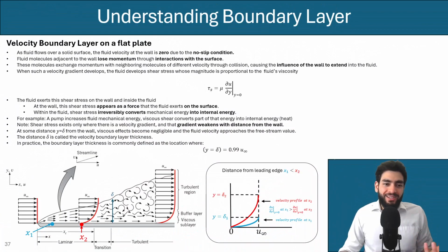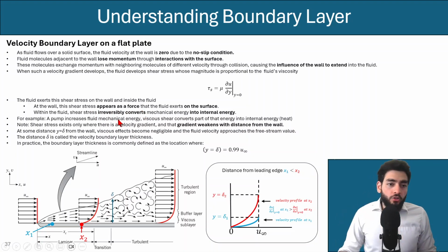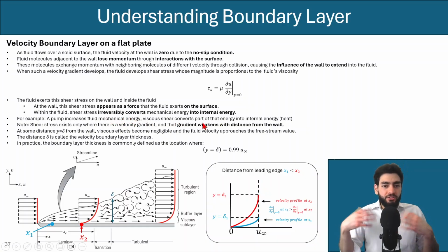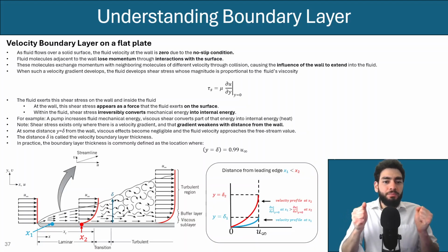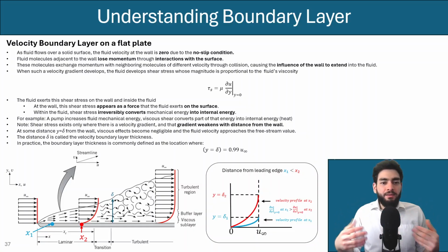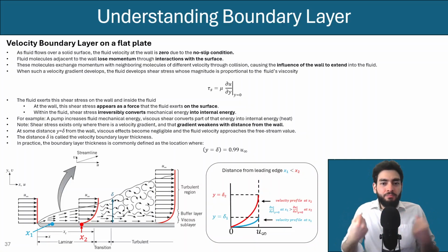So this shear stress appears as a force that the fluid exerts on the surface. Also within the fluid, the shear stress is irreversibly converted into internal energy. So for example, when you size a pump, what a pump does is it increases the fluid's mechanical energy. And some of that viscous shear converts part of that mechanical energy into internal energy that the fluid absorbs as heat.